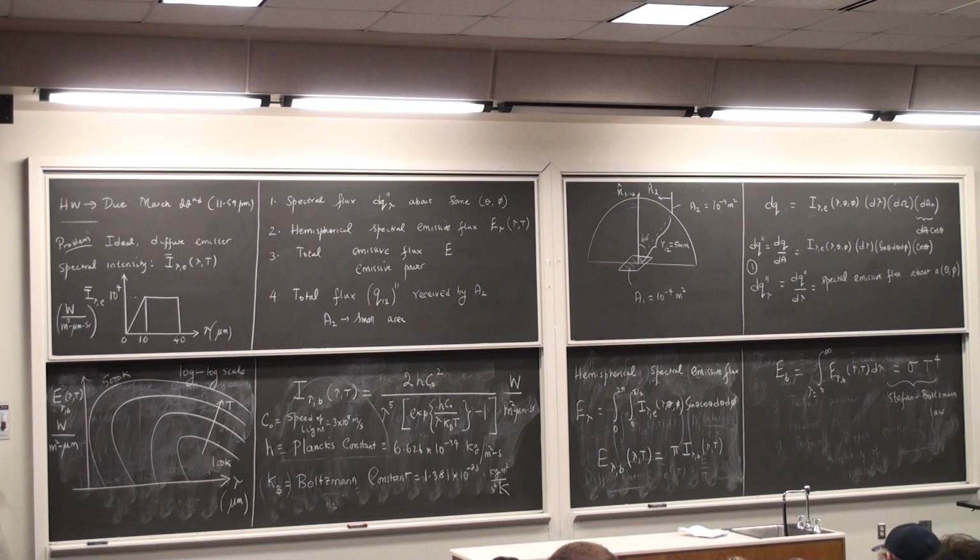The outer surface temperature of the sun is around 5,700, 5,800 Kelvin, and the spectral intensity obtained from the radiation emitting from the sun is closely approximated by a curve between 5,000 and 6,000 Kelvin, which is why the sun is modeled as an ideal surface, because the spectral intensity of radiation emitted by the sun follows in some sense the distribution that is drawn here.